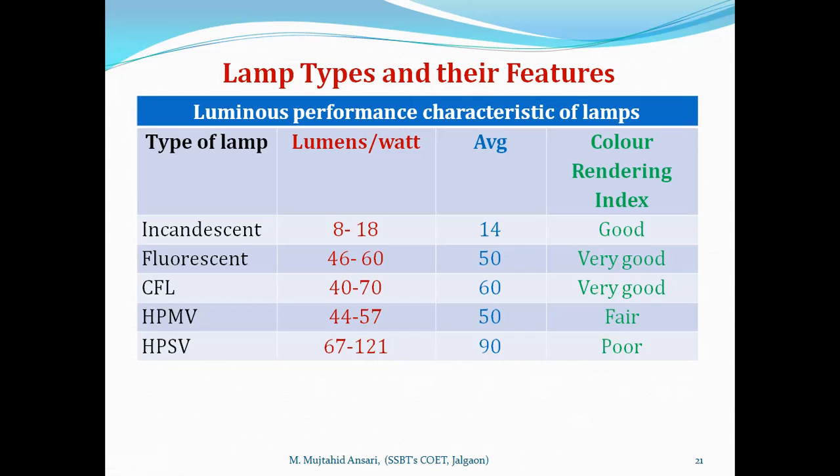The reason is that we have to keep the light away from the petrol and diesel tank from a safety point of view. And when we place the light at a long distance, definitely the light source should be set in such a way that it gives higher efficacy, or the lumens output should be more.